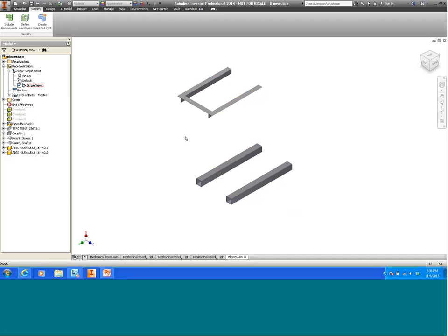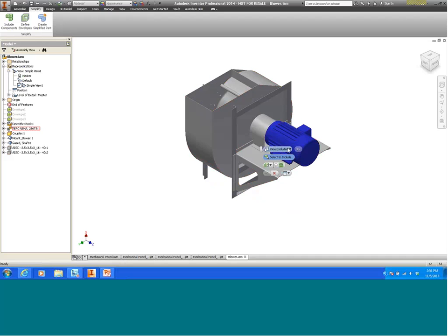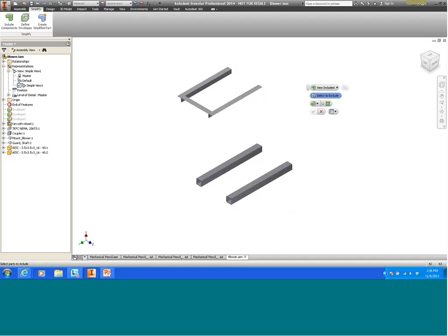I don't actually want those in there. I added them simply to get my size constraints for my envelope. So now I'm going to go in and actually remove these again. I'm going to edit it again. At this point, I'm going to change my selection priority here to View Included. Now, you're probably wondering why the other 3 components aren't included. If you remember, when I created those 3 envelopes, I asked it to hide the original components. So that's what it's done. Those envelopes replace those components.